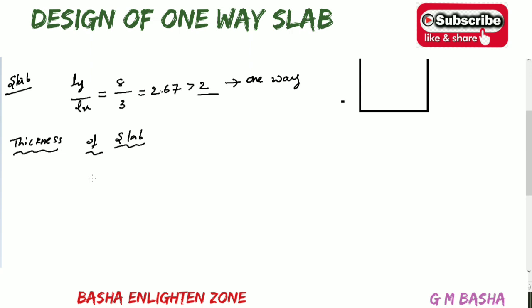But for one-way slabs that are simply supported, you can safely select the span to depth ratio in the range of 25 to 30. So always remember this value. You can safely select it within this range for this type of simply supported one-way slab. Based on this you can take the thickness of the slab, which is D here. So I am simplifying: D will be equal to L by 25 to L by 30.